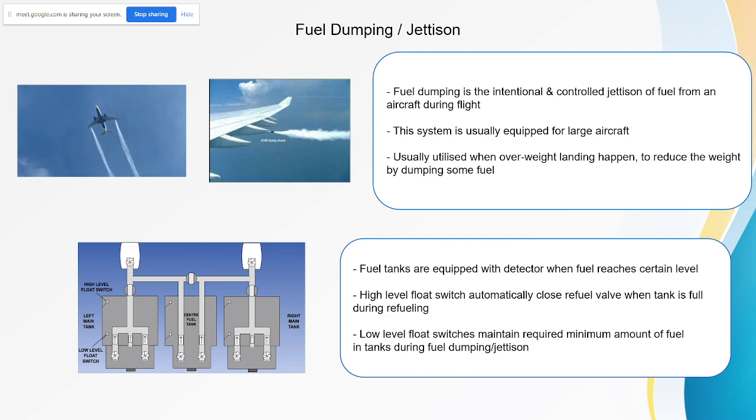Let's say after you take off from KL, something happened. You want to return and land back at KL, but your weight is very heavy, so you need to dump the fuel. That's when the fuel dumping or jettison is done, to dump the fuel to reach your landing weight, so you can land back at KL after takeoff. Any question? Understand?